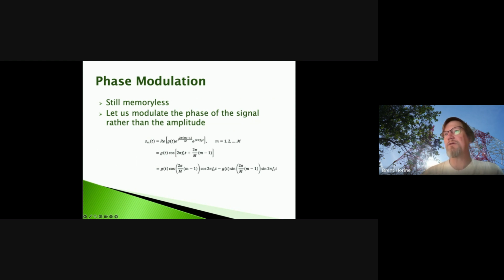All right, so we've got 2 pi radians around a circle, and we're going to distribute M constellation points around that circle, and then we'll iterate from little m equals 1 to capital M. And you can see that if we plug in m of 1, that's going to be 0, so it's e to the j 0. But if we plug in larger and larger values, then we will rotate around the circle. By the time we get to M, it's going to be (M minus 1) divided by M, so we'll almost return all the way around the circle, right?